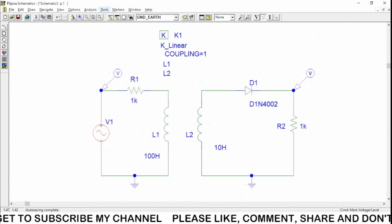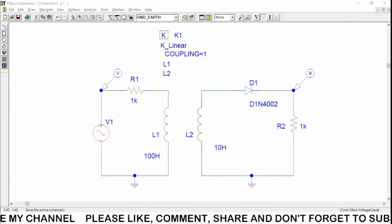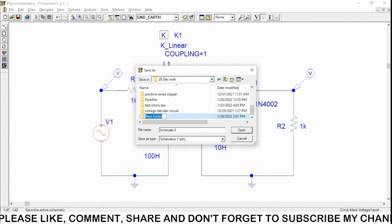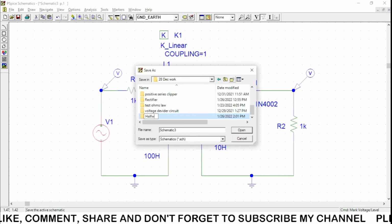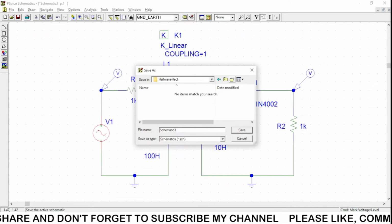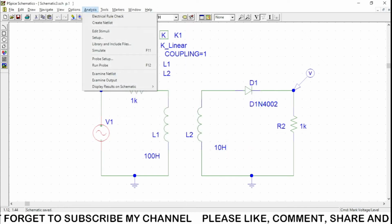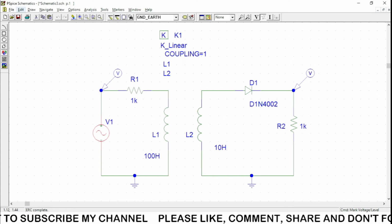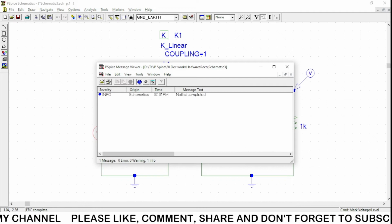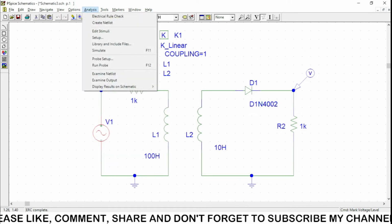Okay, so done. Then analysis, I have to save it first. File, save. I'm going to make again a folder. That folder will be named half wave rectifier. So save it. Then analysis, electrical rule check. You can see the file, view messages. There are no errors, no warnings. Still, from a simulation point of view, they may show some error.